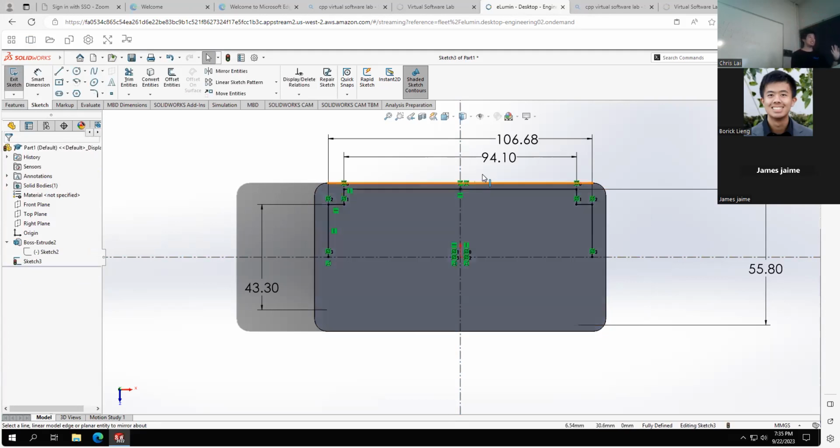Okay, so what you're going to see here is that you know how we had the smart dimensions earlier, right? As I said, I wanted from right here to be 100. You're going to notice that the smart dimension actually reaches from this line to this line, right? So you don't ever have to think in halves or quarters. You just say, oh, I'm thinking that this is probably going to be like 100 something wide, right? And you could just mirror it later after you figure out the dimension, or you could mirror it first and then dimension it later.